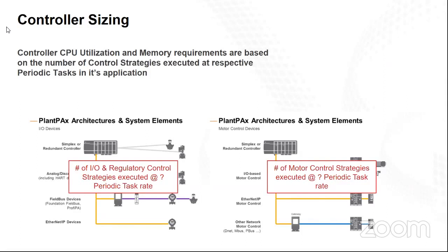Part of it, when you put it in, you tell me that you have so many I/O points, the system's going to estimate how many visualization tags you're going to have there, how many alarm tags. It's all estimated. So knowing your control system and how fast the tasks are going to be is part of the equation of how to come up with a good estimation of what we're trying to do.